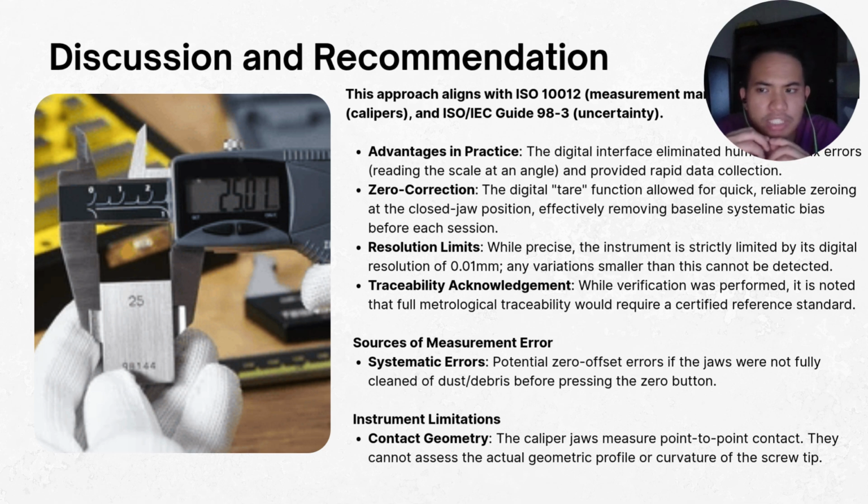So by zeroing the instrument at a fully closed position before each measurement is taken, we effectively remove any baseline offset from our recorded values.